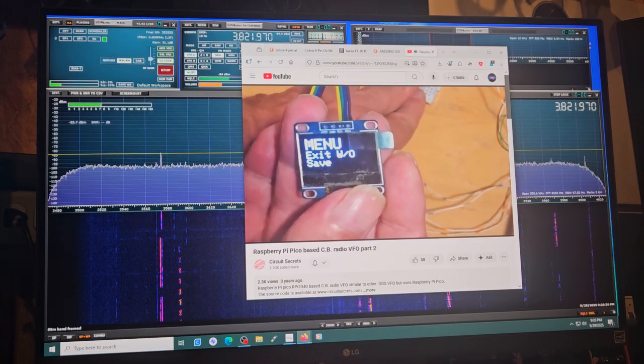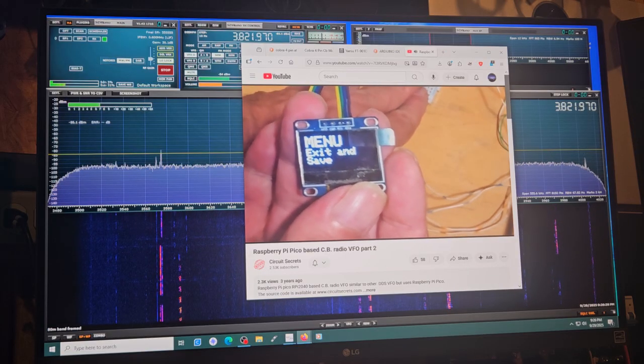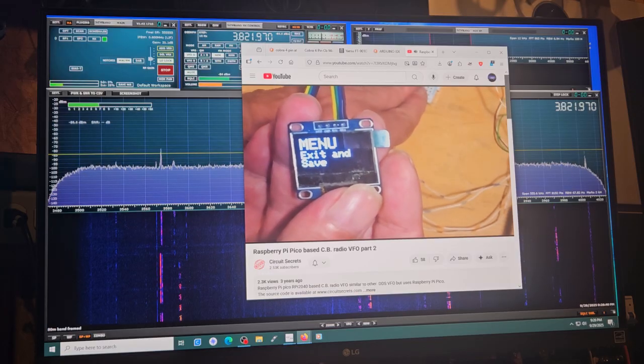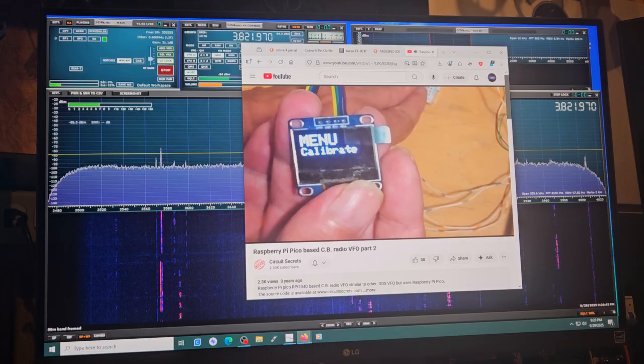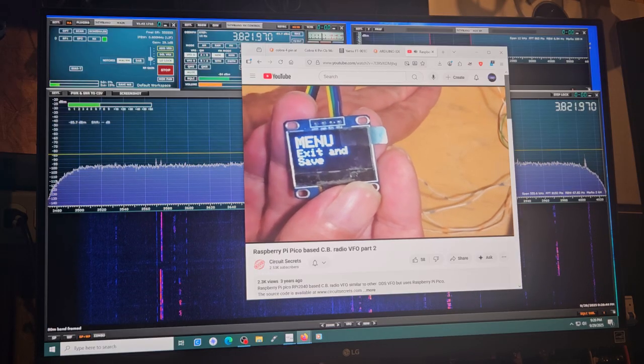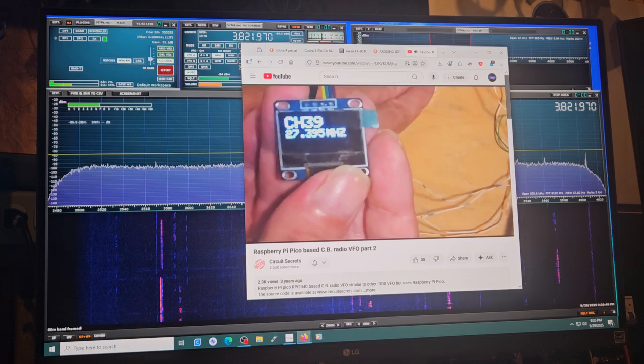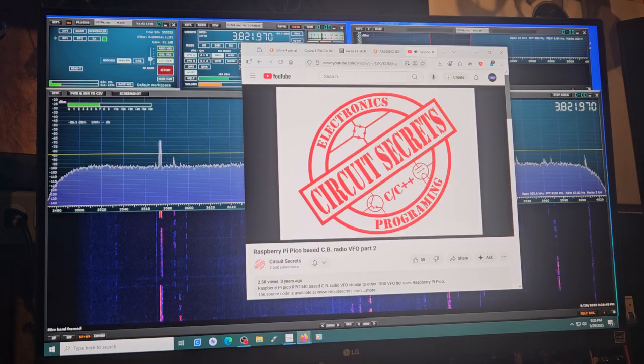Most of this is done with switch statements. I chose switch statements because they are fairly easy to understand and perfect for the 3 states of buttons and 3-mode menu. I think that code is self-explanatory. It is similar to the other display text used in the video I2C Part 2 working with LED displays. The only other interesting change is in this section for calibration. Most of this section was lifted directly from the example code for the SI5351 from the Etherkit library.